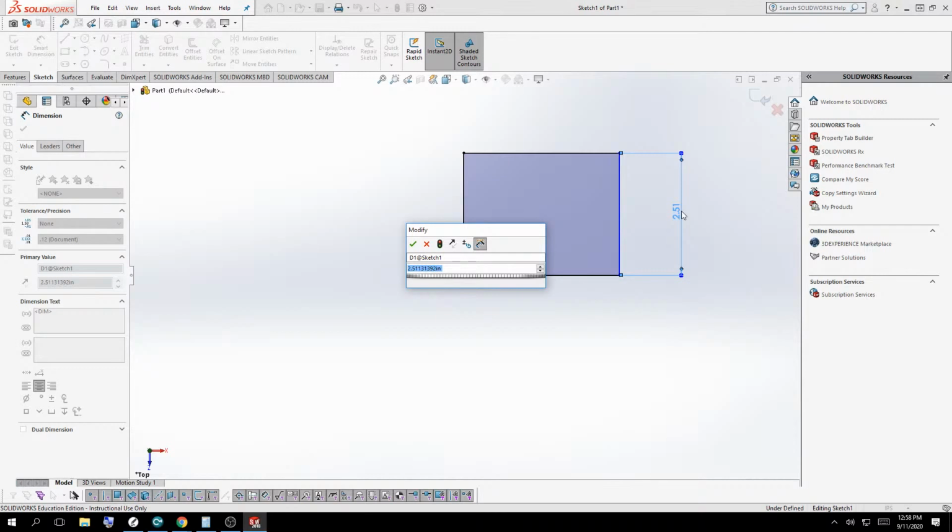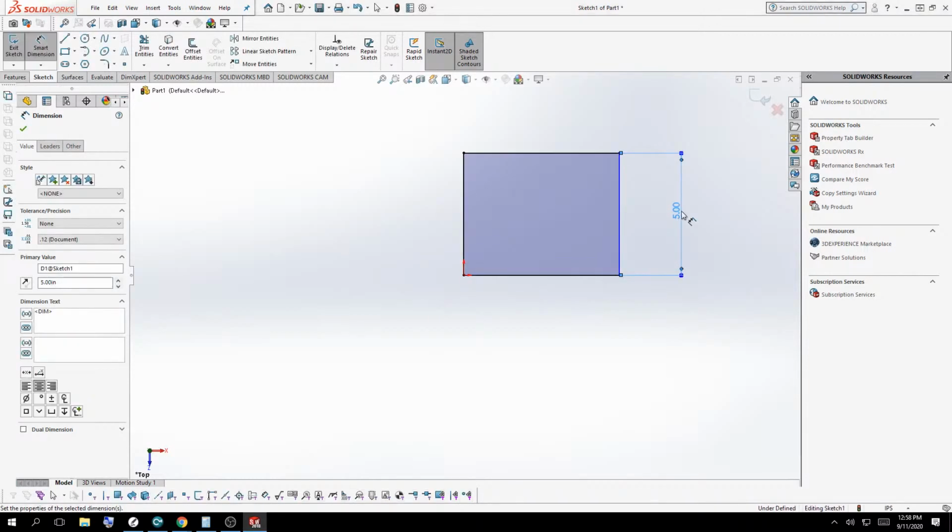So at this point, we're going to regulate this, I believe, to 5 inches. We actually didn't talk about unit regulation at this point. If you are not in inches, or you don't know you're in inches, if you just specify IN, we can ensure that even if you have a metric standard selected, we can be in inches. So when you press enter, you should see 5.00. If you are in a metric equivalent, you will see the metric conversion of 5 inches to whatever metric unit you are set to. It will auto-convert it to the default number value.